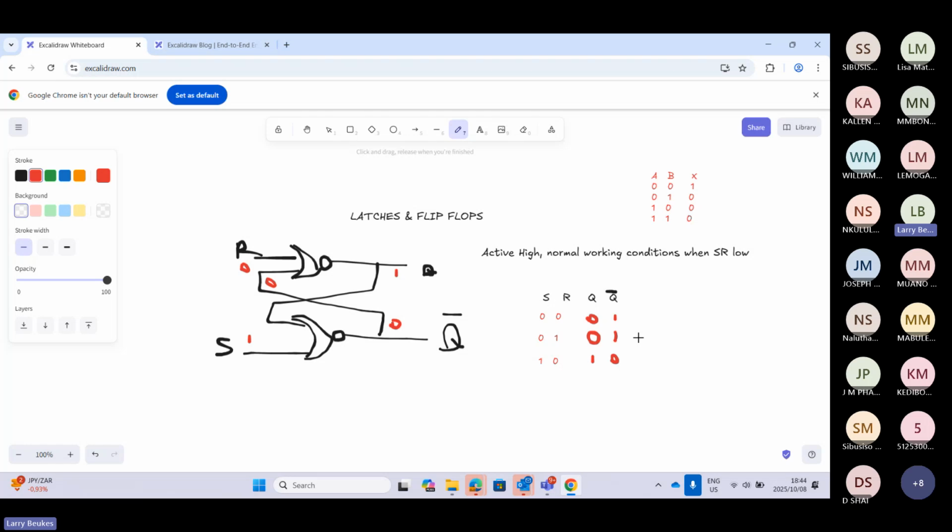So in this case, this one we call a reset, and this one we call a set. How do we see that? Reset, because set is 0, so it's called a reset. Here set is 1, it's called a set, right? So let's just put this comment. Normally when you draw the truth table, most of the time they want you to draw the truth table. So you need to put this comment as well, right? So now we already know two cases. We know this case is reset, and then we know this case is set.